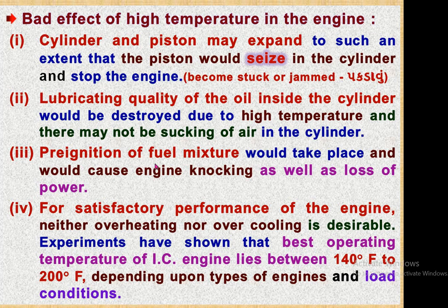Due to pre-ignition of the fuel mixture, if the temperature of the combustion chamber is high, then there will be knocking of the engine system, and due to which we will lose the engine power. For satisfactory performance of the engine, neither overheating nor overcooling is desirable.